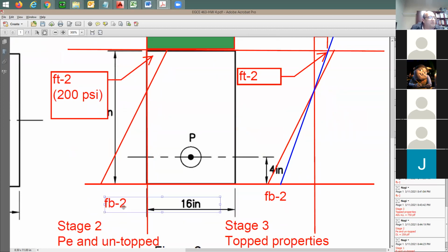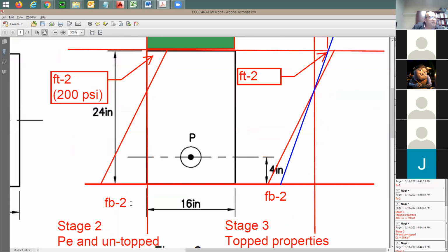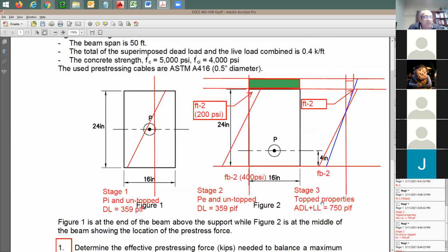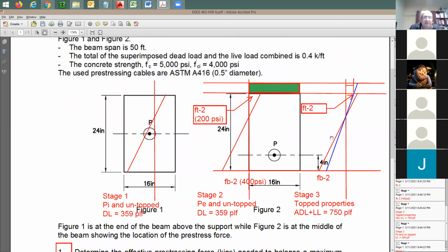And this bottom value, I'm going to say, is about, let's say, 100 psi. No, not 100. It's going to be much higher, right? According to this scale, this is going to be 400 psi. Just because of the effect of this additional dead load and live load, when you divide by S top and bottom, there is no axial load effect here, right?